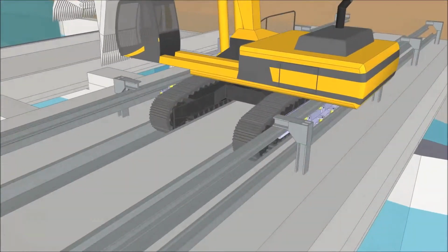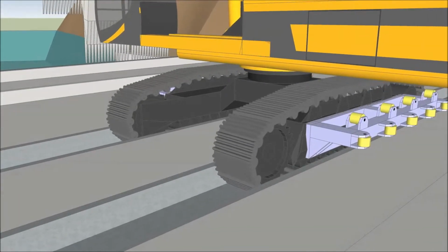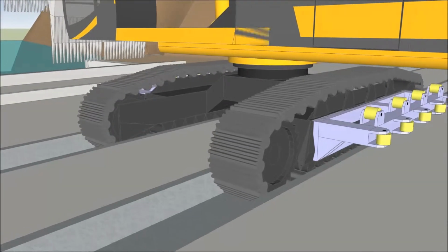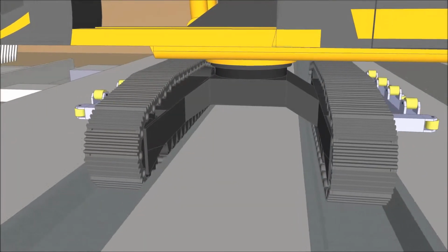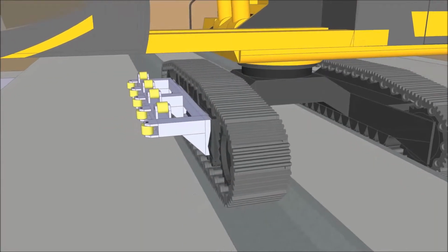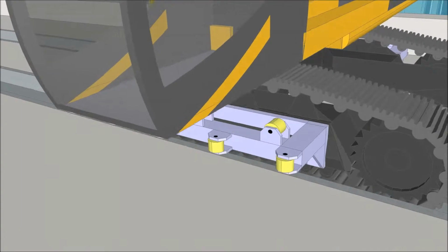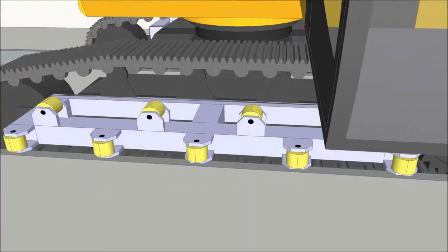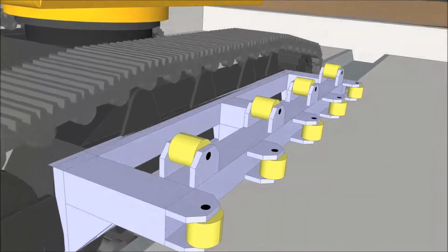There's a roller guide assembly installed on both sides of the chassis. They're mounted directly to the track frame. These rollers are to be in contact with the guide rail assembly in 2 different angles. The roller guide assembly and the rail guide assembly, along with the tread track guides in the bottom, prevent the working machine from vertical movement and from horizontal movement off of the travel path.